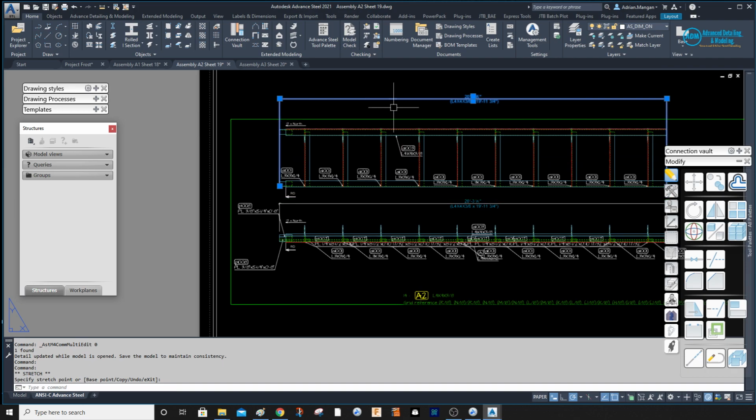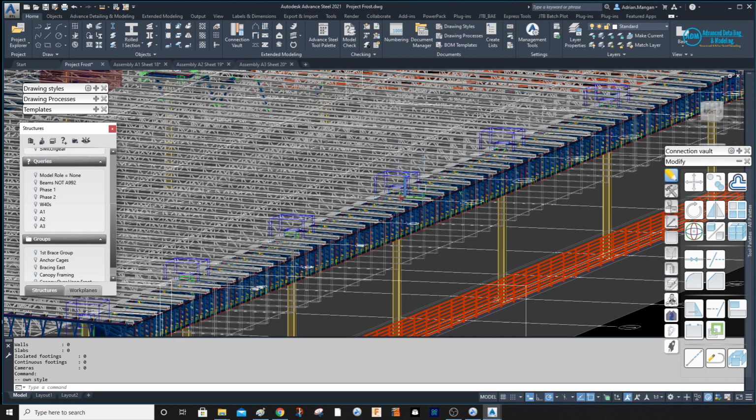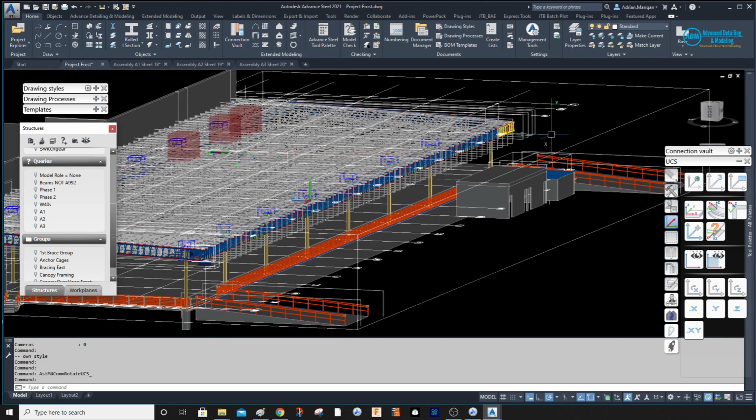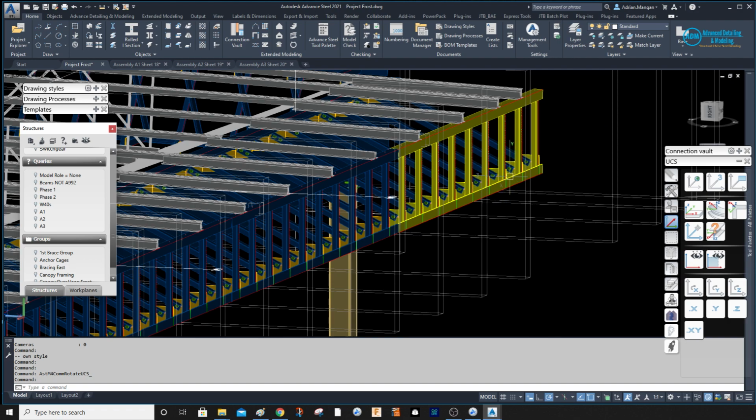What I have done is I set my UCS up, and you can see I want to rotate through the x-axis, and that's the way I want to view. So I want to view looking in from the z-axis. I want to view my part looking in through the z-axis from the inside of the building this way. And that would mean that this will be flat, this will be vertical, and this will be twisted a little.